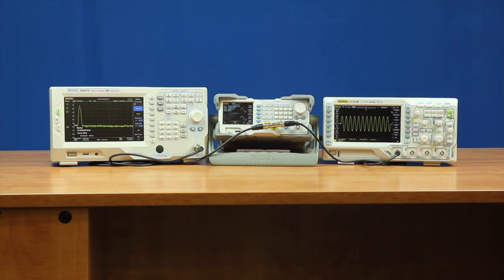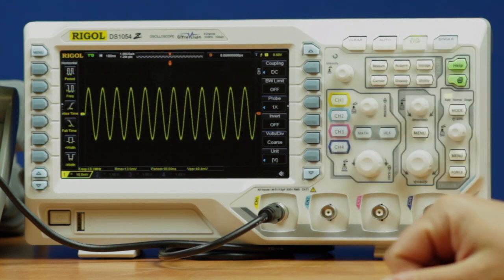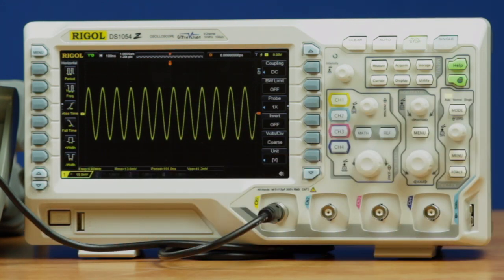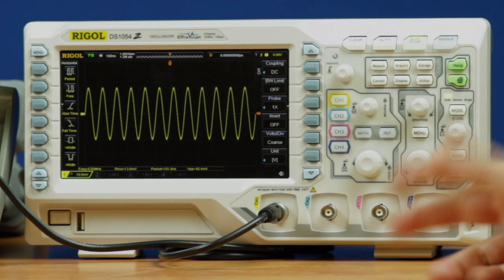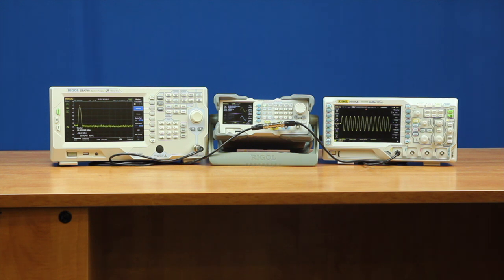So here's our most basic view of a signal in both the time domain and the frequency domain. We're generating a basic 10 megahertz sine wave. On the scope, we can see the sine wave, and this is 100 nanoseconds per division, so we can label the frequency at 10 megahertz. We can see that you get one sinusoidal wave every division on the screen. We can also see the amplitude here expressed in voltage, either volts peak to peak or in volts RMS. If we look at the spectrum analyzer, we see our 10 megahertz expressed as a single peak on the left side of the screen there at a power level in dBm. So the analyzer talks about this signal as a single peak in power, whereas the scope talks about this as an alternating signal over time in voltage.